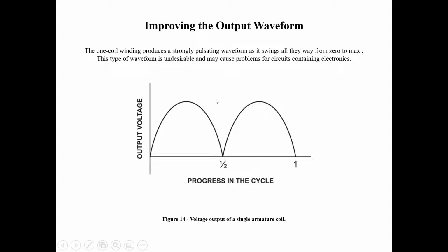Also important to touch on is that in DC generation, even though we have this pulsating DC where we don't have the negative alternation, the armature winding is still spinning 360 degrees. So technically it's still generating AC. It's the split rings that output it as DC. It's not like we're just going back and forth from 180 to 0, not doing a full revolution. If it's attached to a combustion engine, it's still spinning on a 360-degree circle. But the output is pulsating DC, and it's still a full 360-degree revolution. Whether I'm talking AC or DC, it's the split or slip rings that determine the output.